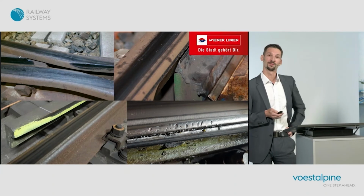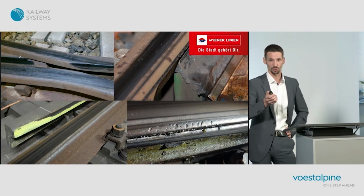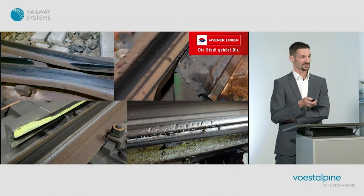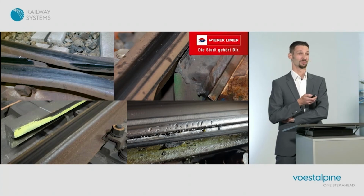And the fourth photo on the bottom right shows you RCF defects. I would call them spalling, not head checks, but spalling, which were maybe introduced or caused by the excessive use of lubrication or the lubrication device itself.